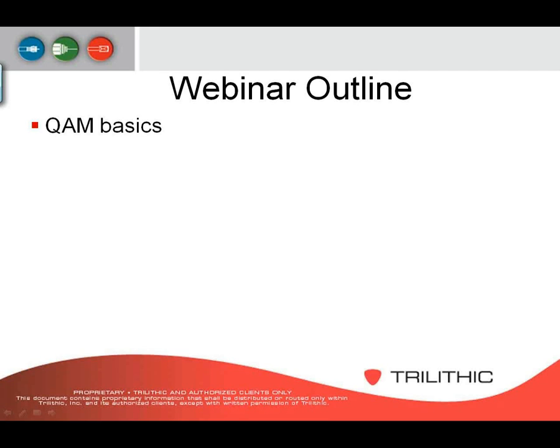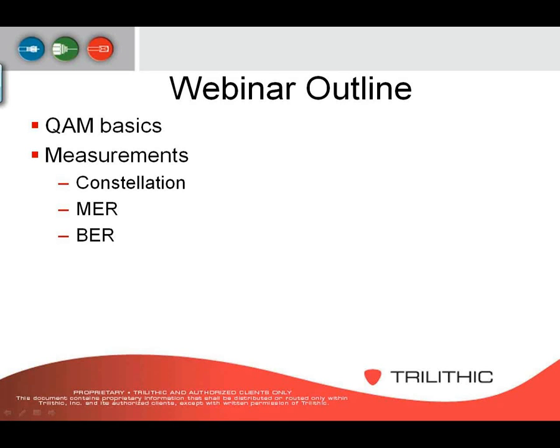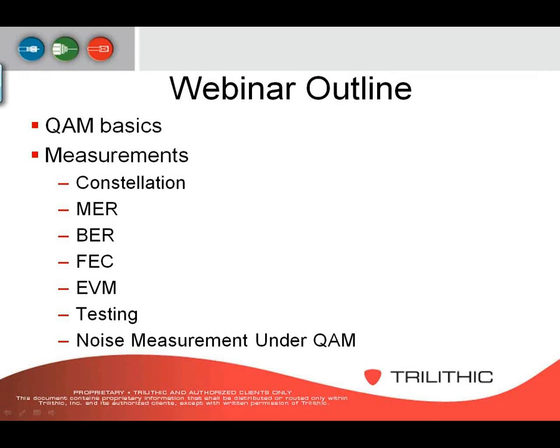As a webinar outline, we're going to talk about the QAM basics. We'll talk about measurements, different types of measurements using constellation, looking at constellation patterns, MER, BER, the FEC, EVM, and then we'll just talk about testing and noise measurement under QAM.